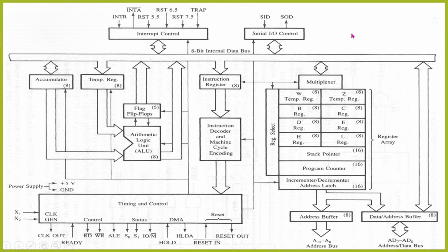Whatever instruction or application program you are writing, the microprocessor will repeatedly do these 6 tasks, not in a predefined order, but depending upon your instruction. It will repeat these same 6 functions for every instruction. Every instruction will have opcode fetch as one compulsory machine cycle. The next machine cycle will be based on the meaning of the instruction.